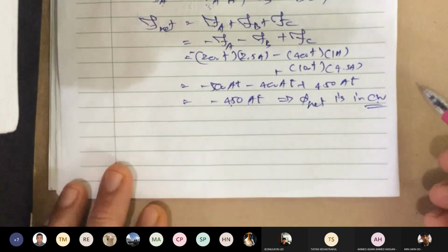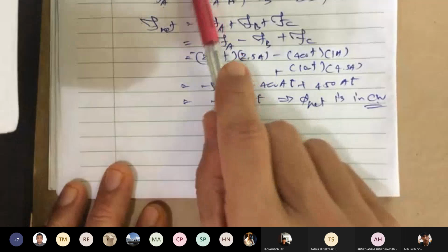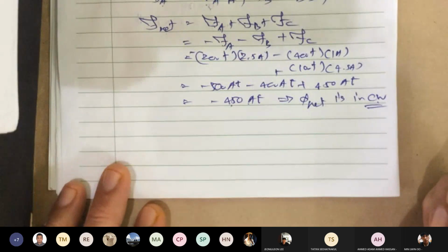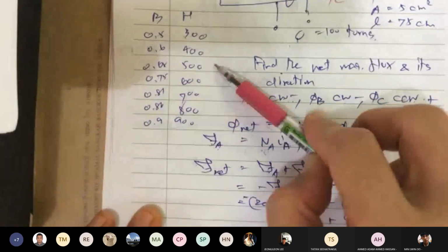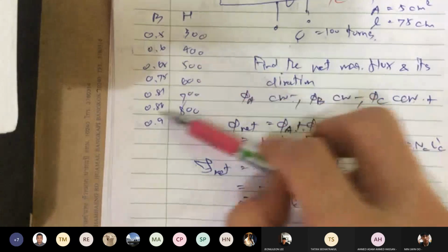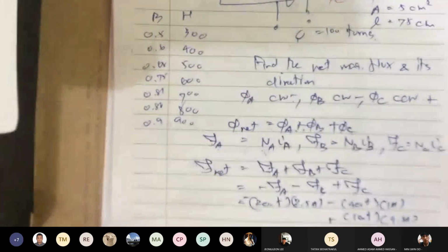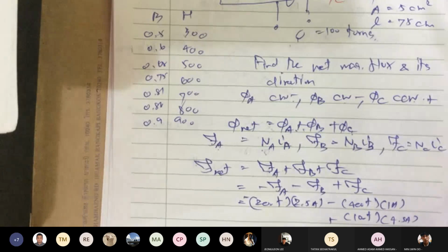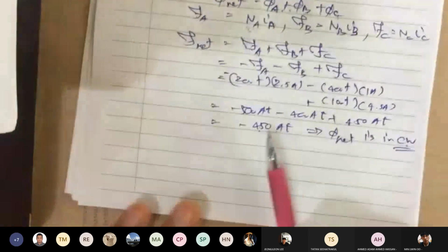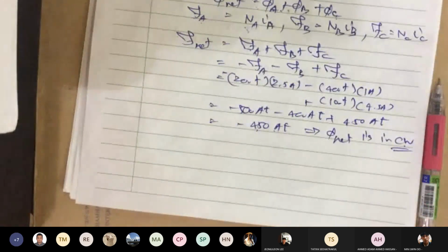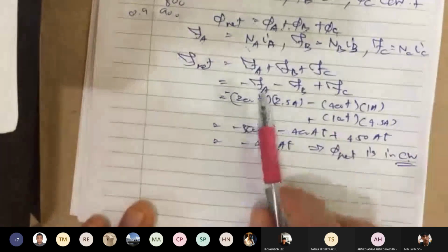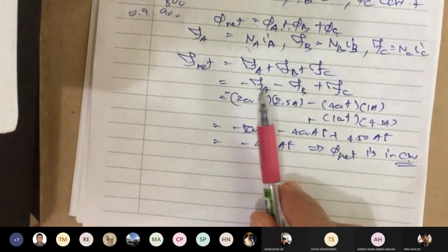Okay. Now, what about phi, the magnetic flux? We have to use a table given to you that depends on the core material. Okay, a B and H table, so you don't need to know mu, or you can calculate mu using the ratio of B and H. But to do that, first you have this number, the magnetomotive force. What does that have to do with phi? So how do we do this? You have to use Ampere's law, if you remember.